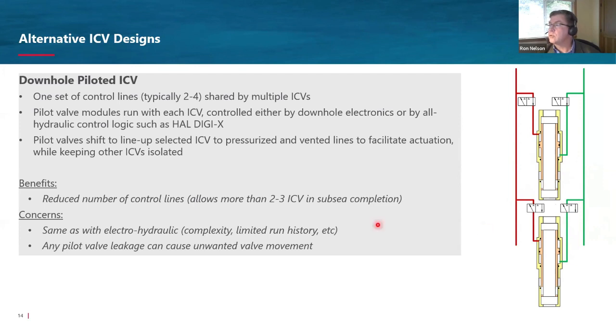It comes with concerns. You have a lot of complexity once again, whether it's electronic or hydraulic operations. And another thing as well is if you have any leakage across these pilot valves, which can happen, you can get uncommanded valve movement from that as well. But I know Halliburton have got what they refer to as their DigiX system, and they've got a few of these in the ground, and I think they've worked quite well.